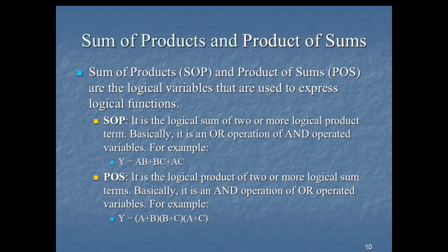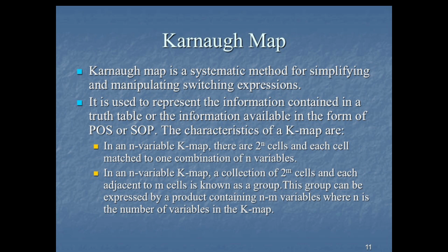Last but not the least, we talk about the K-map technique. It is also one of the techniques we use to simplify a Boolean expression, a logical expression, and thus to minimize the expression, so that the number of gates required for implementation of the circuit is also reduced.